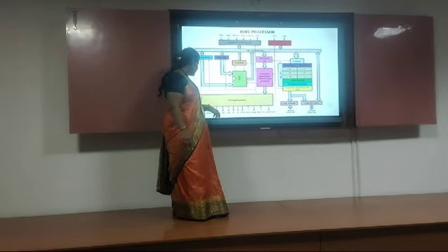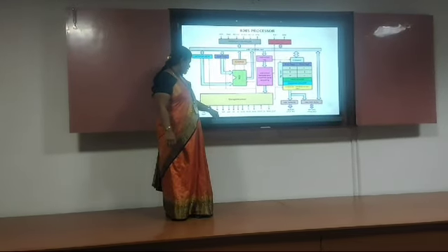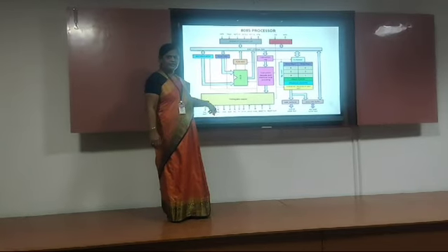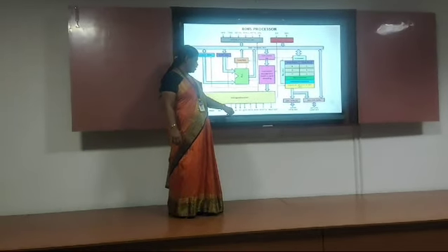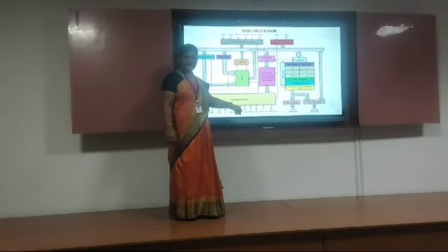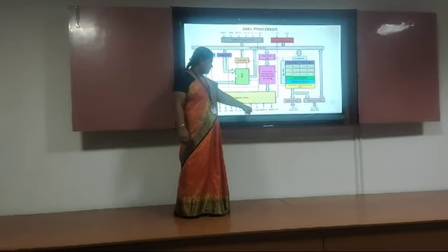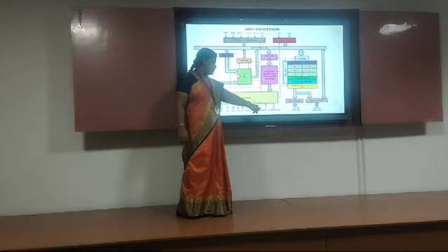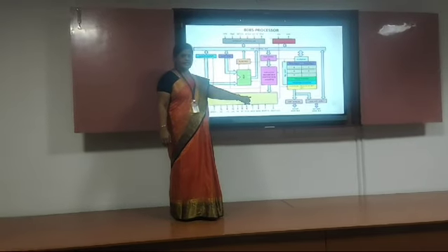So we have various signals here: ready, read, write, ALE. All are control signals of 8085. S0, S1, IO/M are status signals of 8085. Hold and HLDA signals come under DMA. Reset in and reset out come under the reset signals.